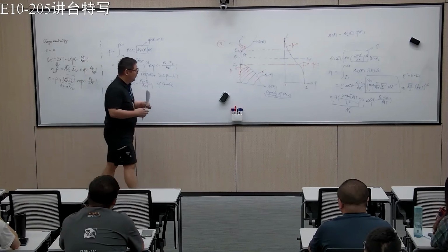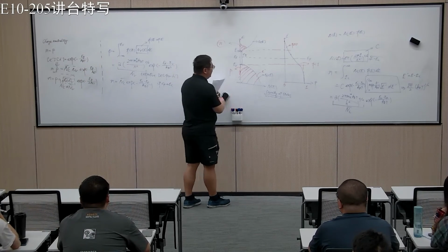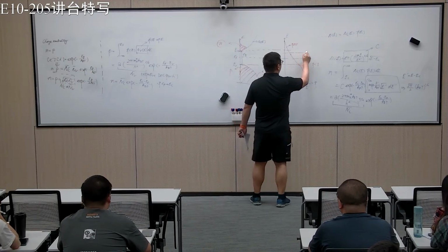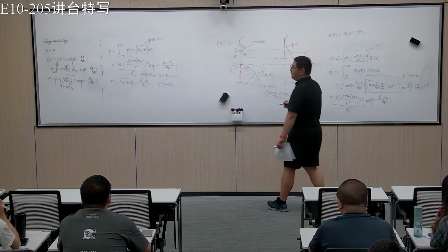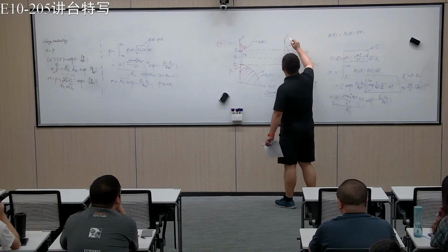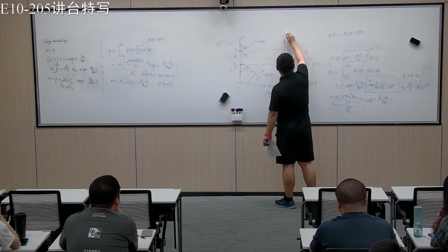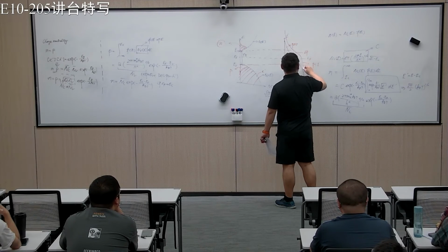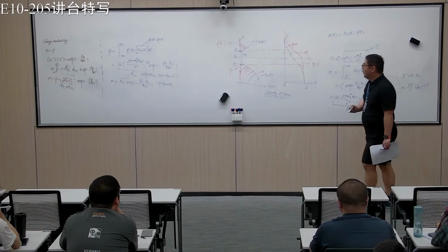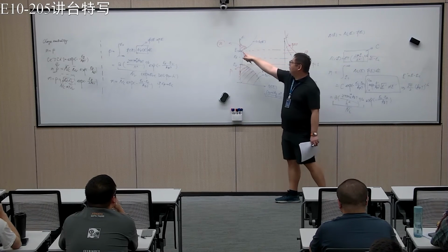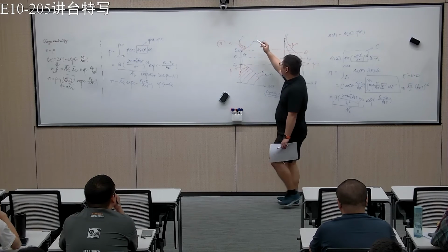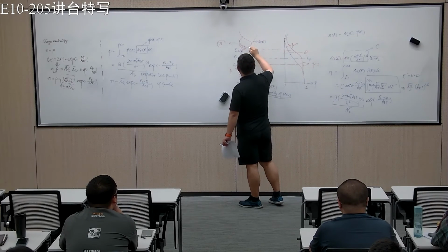Basically, if I increase EF to here, this function will change from here to something like here. So what it does is, if you look at the states in the conduction band, now you have an even larger number of electrons.